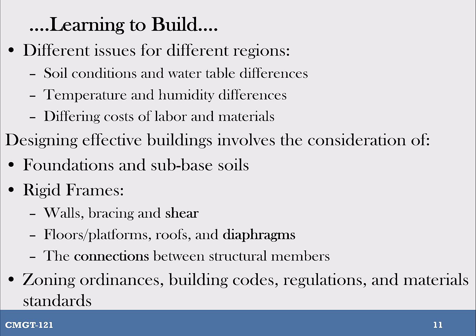Yes, there's soil conditions. We have to worry about that in Louisiana. We have very soft soil, and so buildings tend to settle. So you have to think about making your foundation strong like a raft, so it can afford to tip and shift and sink without breaking apart. The vast majority of house foundation cracks come from just not putting enough reinforcing in the slab, or putting the wrong kind, or not having a deep enough perimeter grade beam system running around the outside or underneath load-bearing areas inside.